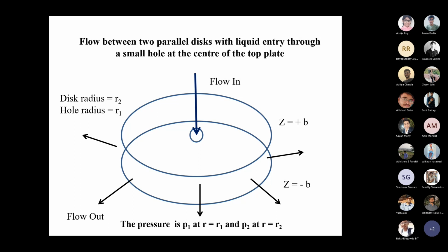When can we neglect that? If the flow rate is not too large, if the velocity is not too large, then we can do that. If it's liquid of high viscosity, then also we wouldn't introduce too much of an error when we assume that, because viscosity is something which brings back order to a system. So a high viscous fluid will create a condition in which all the disturbances die down very quickly, and then it starts to move radially outward. But this is the point where we must appreciate that we have made an approximation in this.